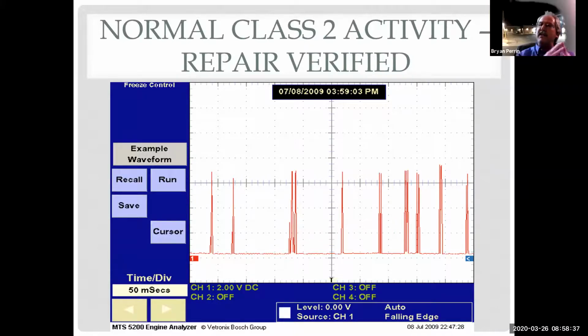We got that information out of the repair information from the manufacturer. So I can get that on All Data. I can get that out of specialized books or training classes I teach. I could probably find it on the internet. I could find it on SAE because they have published documents for the J1850 protocol on how it works. So the short answer is research. You could probably even Google it and get some information or some known good patterns on what a car that talks is supposed to look like.